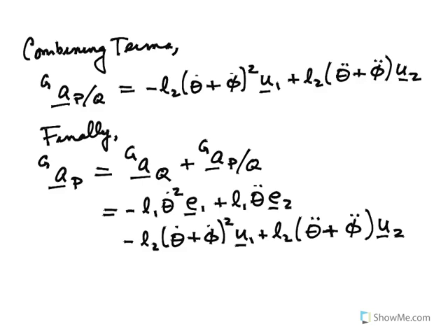The second part of the vector, which are terms 3 and 4, which are expressed in the basis u1, u2, u3, which is fixed in the second arm, those terms actually identify circular motion of point P relative to Q. So in other words, it's giving you the circular motion of how P is changing relative to point Q, and those computations are more conveniently done in a basis that's fixed in the second arm.